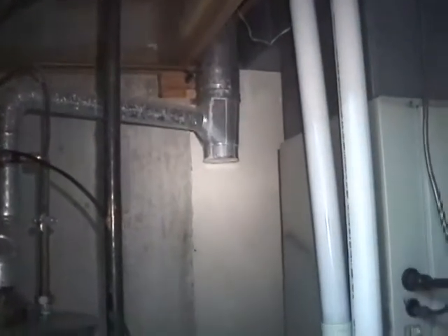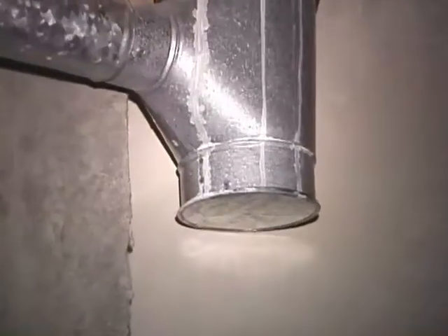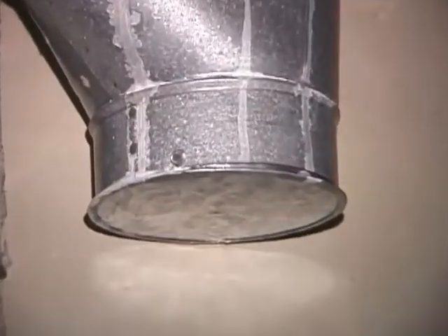This new high-efficiency furnace was installed and the water heater was left connected to the original 6-inch B vent that had also common vented the old furnace. Notice the staining from condensate dripping out around the B vent and over the connector and new cap. This has all occurred in just 1 month since the new furnace was installed.